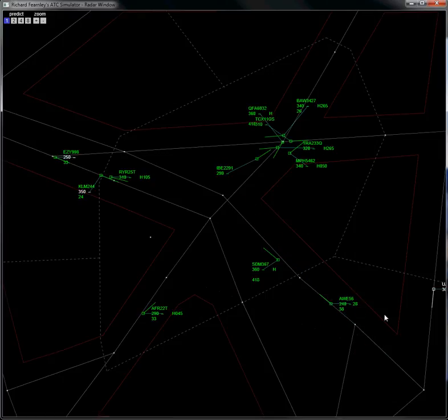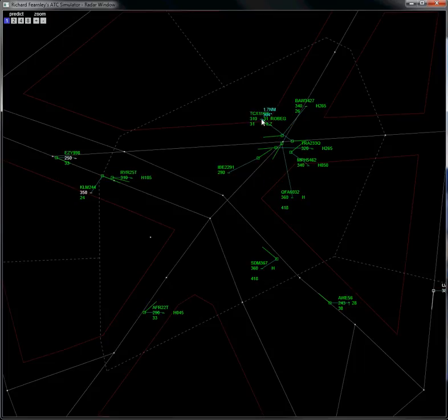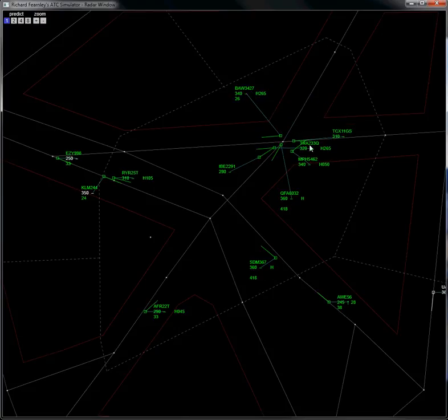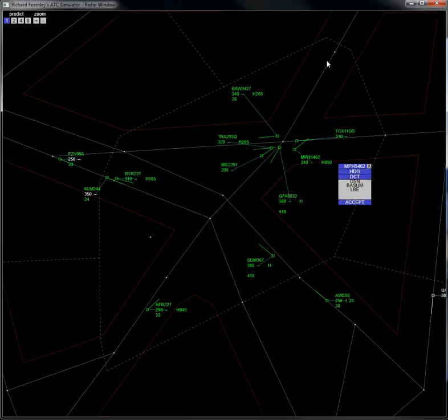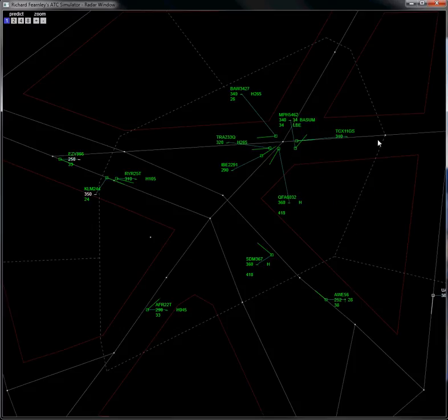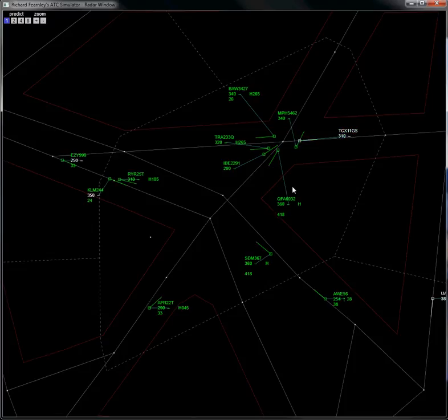I now have a bit of time to check the situation up here. I'll do that first by sorting out the labels, as they're all starting to overlap. So I checked the Martinair and the Speedbird have now passed at flight level 340, so I can resume this aircraft direct to Bassam, which is this point up here to the north. The Kestrel 11 Golf Sierra, there's no traffic affecting him, so I can transfer him. I do that by right-clicking and the aircraft turns white.